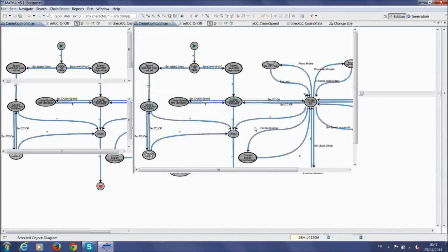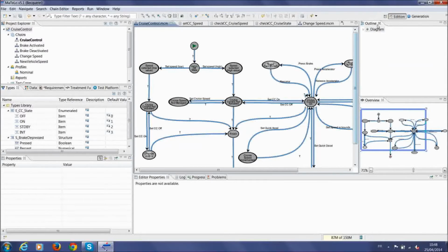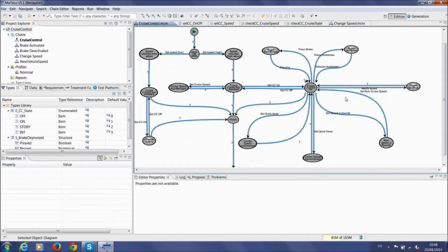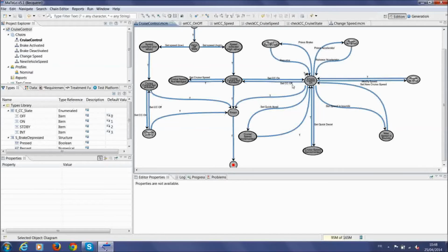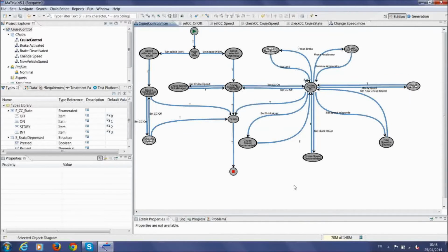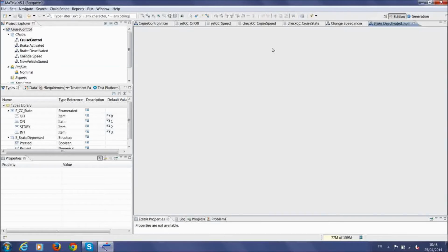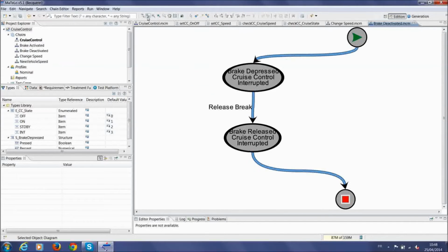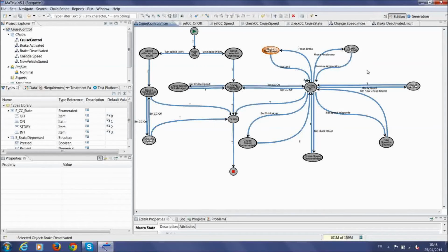You can associate several inputs on the same stimulation of a transition. The process is the same for the outputs, except that the association is done with the Verification tab. To associate one or several requirements to a transition, select the Transition tab and then Requirements. Choose a requirement that you wish to associate from the requirement library, and drag and drop it in the editor window under the title requirement.